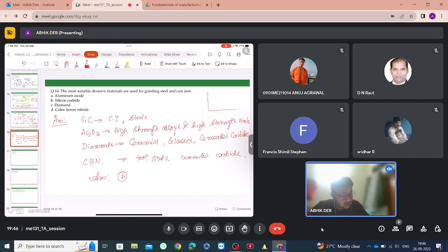See, this is a low strength alloy, this is a high strength alloy. If this plastic deformation zone exists, then it is ductile. And if the stress strain curve is something like this, just this much, then it is not ductile.